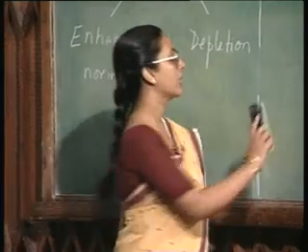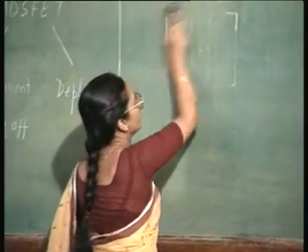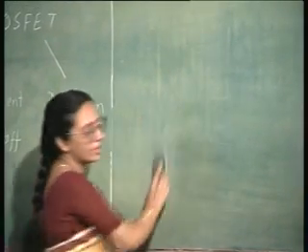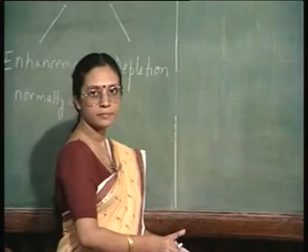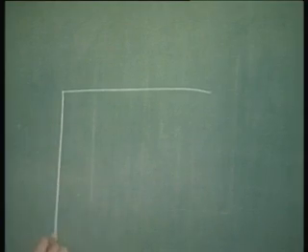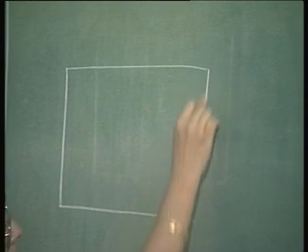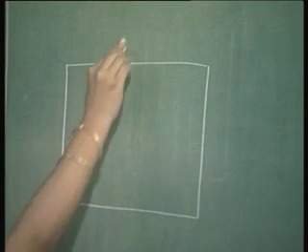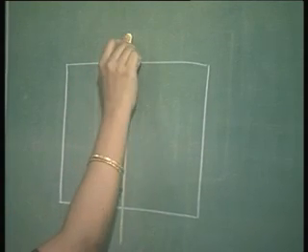That is why we can start with defining the gate, that is, the first mask is where you open the window in the field oxide, step A, and then you grow the gate oxide, deposit the polysilicon and then pattern the polysilicon using a mask like this.